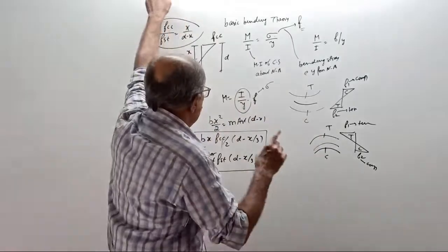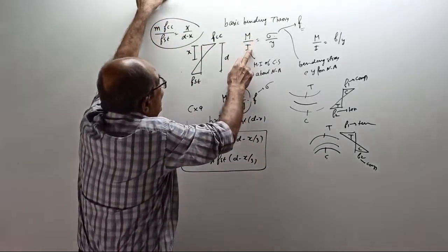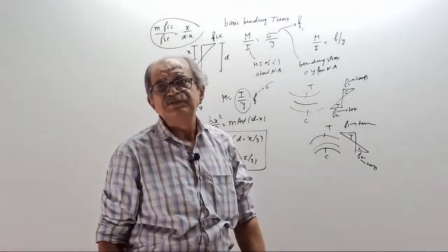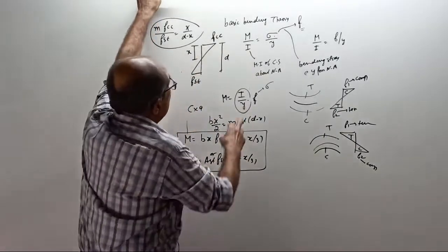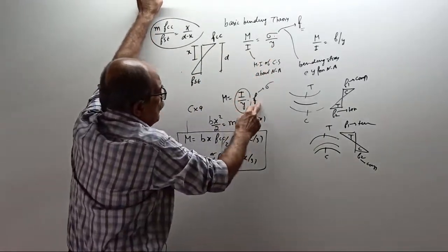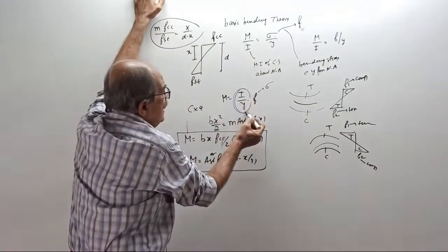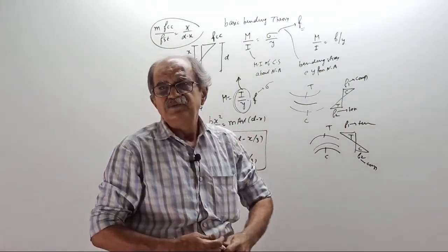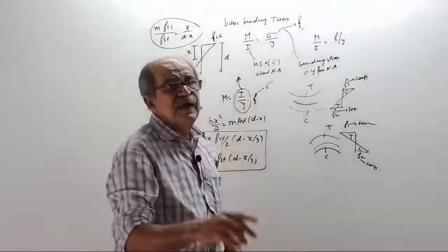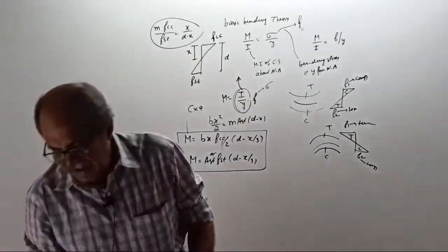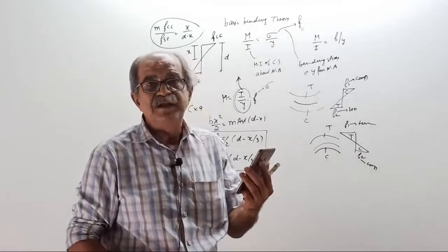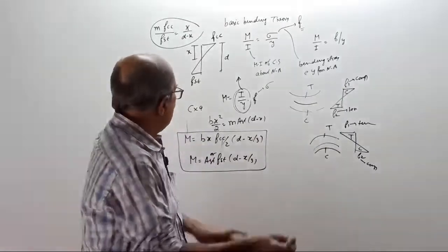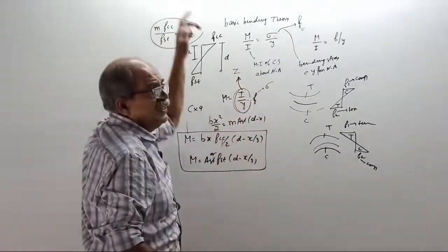So the question was, in bending theory, moment of inertia is used, but in RC theory, moment of inertia is not used. Correct, they will tell. See, no divide. See, M by I equal to F by y. Actually, remember, this I by y in strength of materials, what is it called? Tell me, if you remember. I will go slowly. This I by y, there is a name. Anybody know it? I by y has got a name. Yes, it is called section modulus. I will come to it, Z or section modulus.